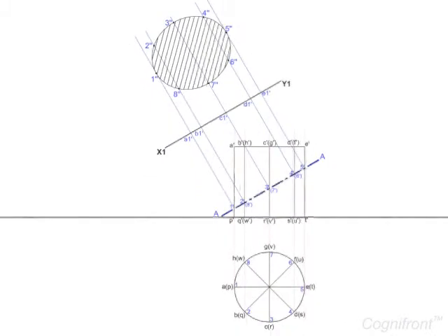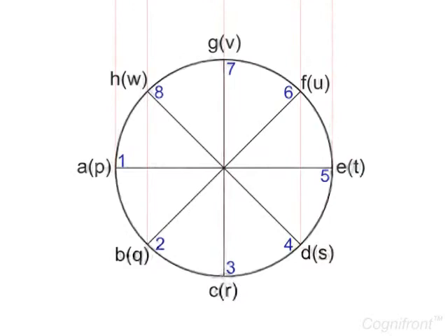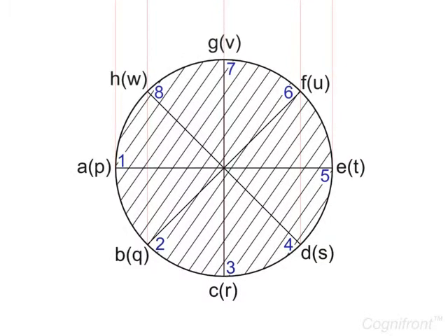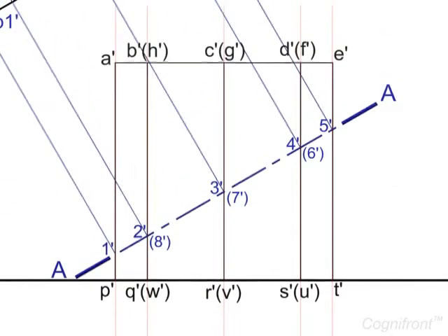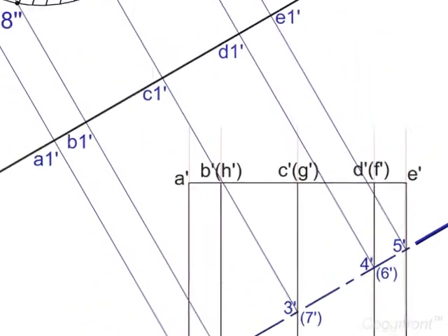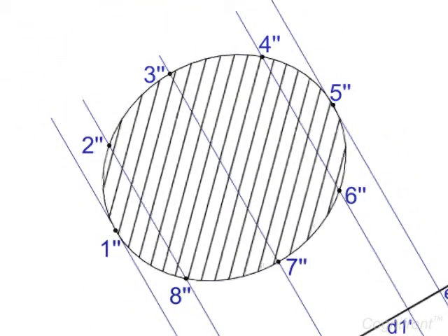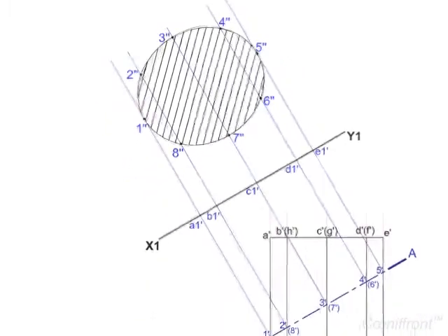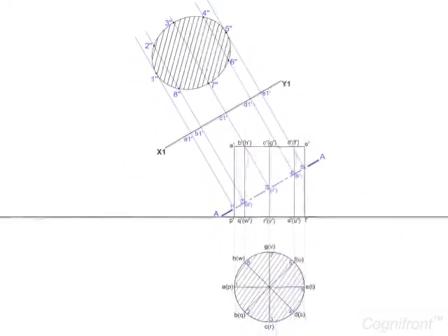Observe, as the section plane cuts across the whole section, the plan itself is the sectional view. So friends, the sectional views are truly helpful in building internal and hidden features of the complex mechanical parts. The cutting plane technique gives the true shapes of the cut sections by revealing the interior elements of the solids.